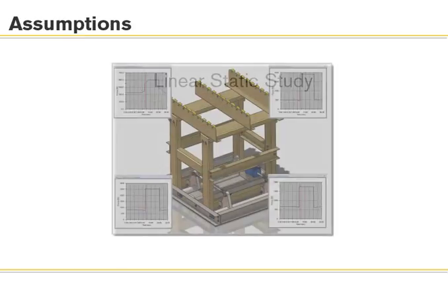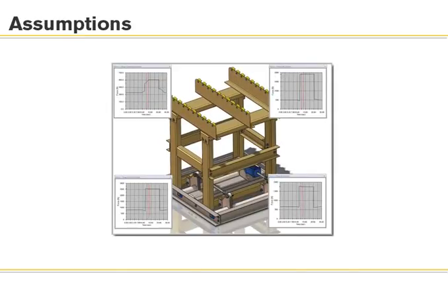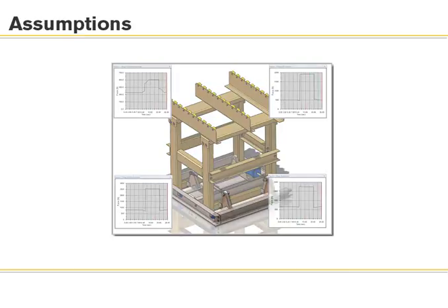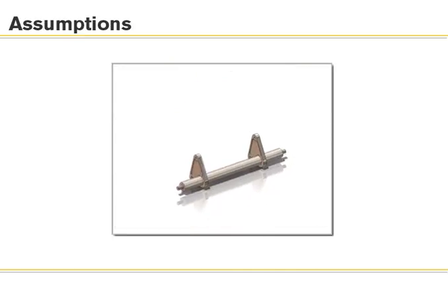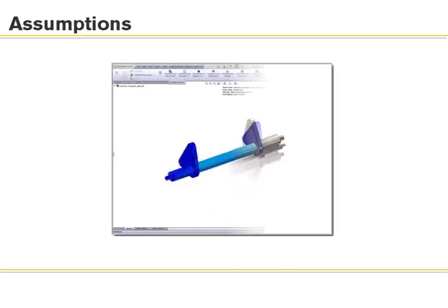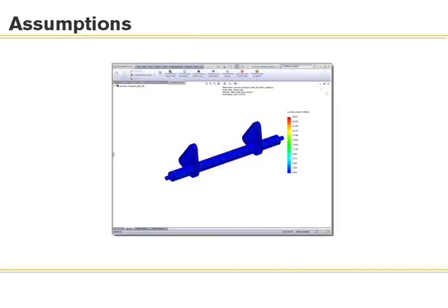You can test assemblies using the full version of SOLIDWORKS Simulation, and with full simulation, you can even determine what kinds of loads a part will experience from its interactions within an assembly. Once you know what these loads are, Express is still a great tool to test and validate the part by itself. Now, I mentioned that Express can perform a linear static study.